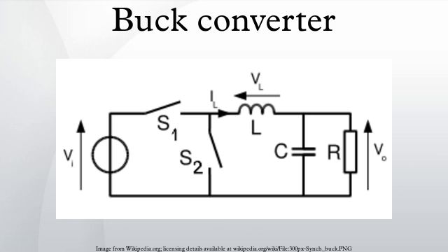Over time, the rate of change of current decreases, and the voltage across the inductor also decreases, increasing the voltage at the load. During this time, the inductor is storing energy in the form of a magnetic field. If the switch is opened while the current is still changing, then there will always be a voltage drop across the inductor, so the net voltage at the load will always be less than the input voltage source.